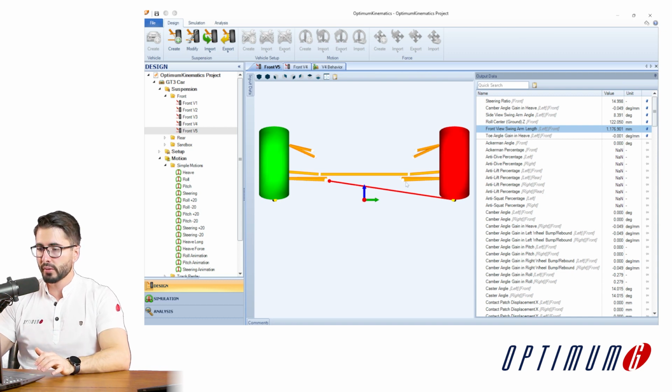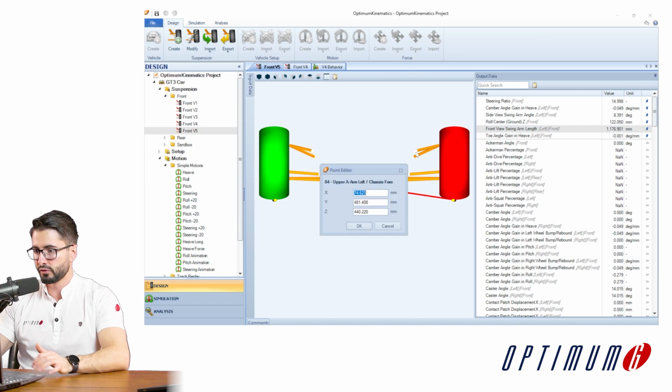So we have to change our pickup points in order to make this point a little farther away from this tire. So a clear option, since the instant center is the intersection of the plane of the 2 wishbones, would be, for example, to raise the 2 pickup points from this wishbone. Just like the previous episode, I'll show you first a manual iteration, how to do that manually, which is not very efficient. And later on, I'm gonna show you how to use an optimizer for that.